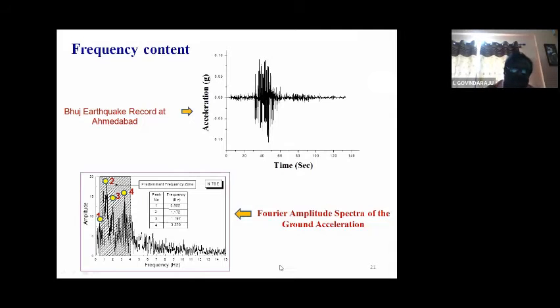damages in structures. See here, we converted this time history of acceleration into frequency response form. So this is the amplitude, and we identified several peak frequencies, say 1, 2, 3, and then 4. These were the resulting frequencies from the earthquake, spikes, and the predominant frequencies. The first is as low as 0.85 or 0.86, and the second is around 1.172. Third is approximately 2. Fourth is this.